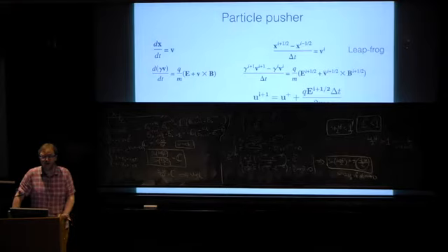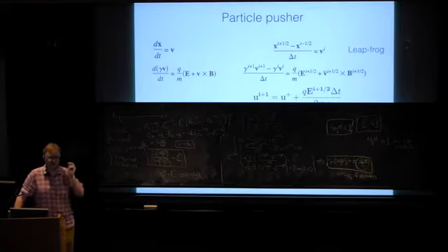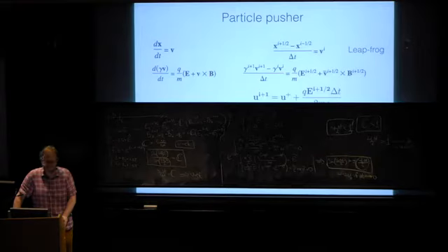So that's, I would say, the only sort of well-defined advantage of implicit codes compared to the explicit codes. They're much more computationally expensive, so I would think a lot of times before actually trying an implicit calculation.